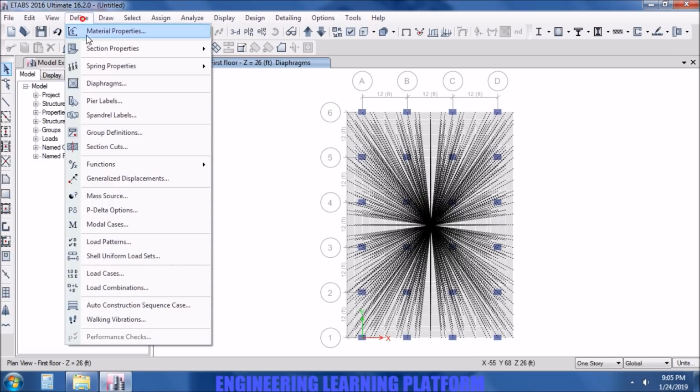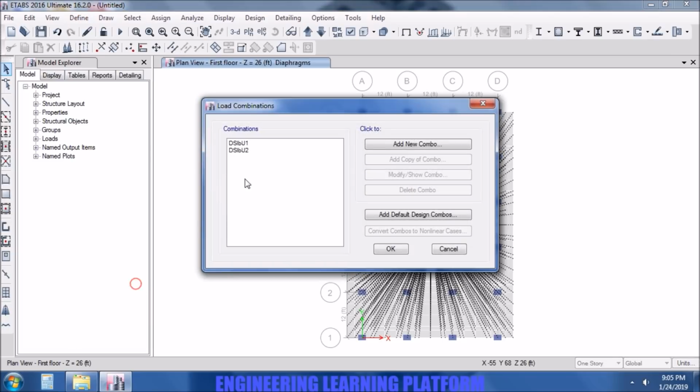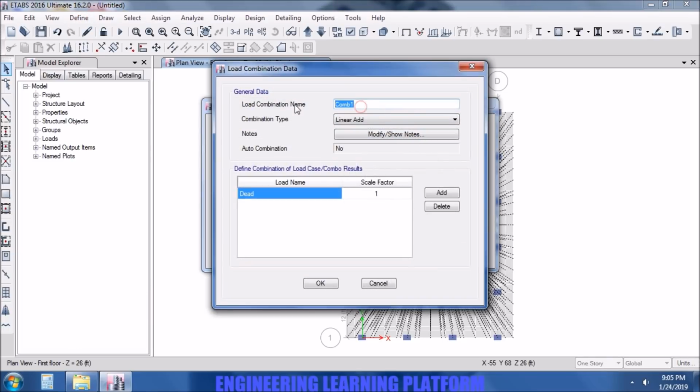Now the next step will be adding a long-term deflection combination so that we may apply the check for the deflection on the slab, which involves a factor of 3 for the dead loads usually, conservatively, and a factor of 1.5 for the live loads.